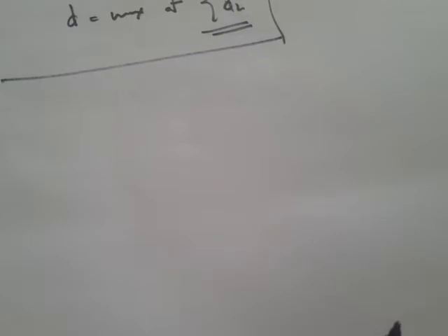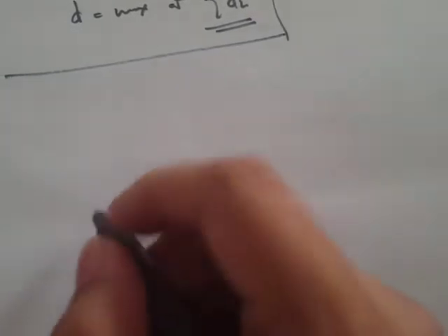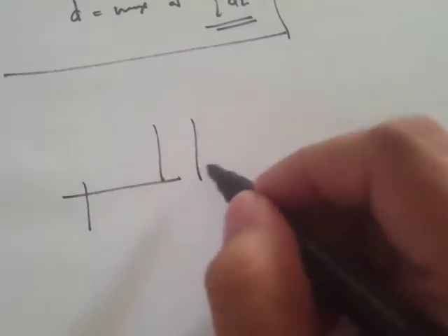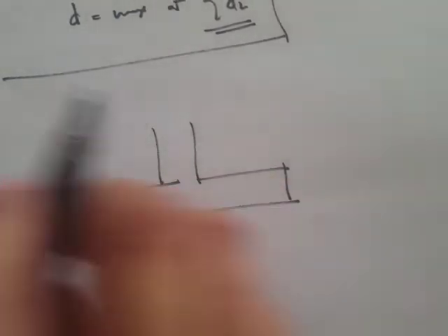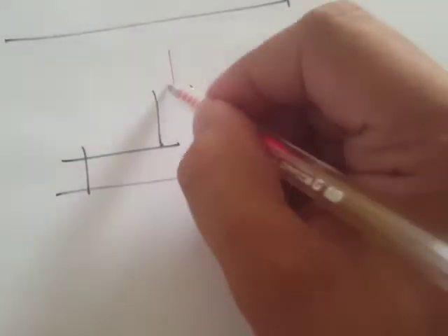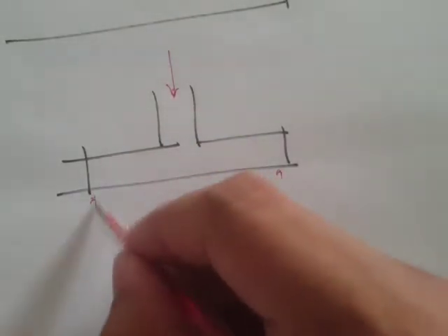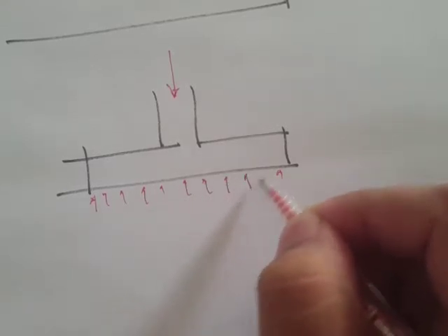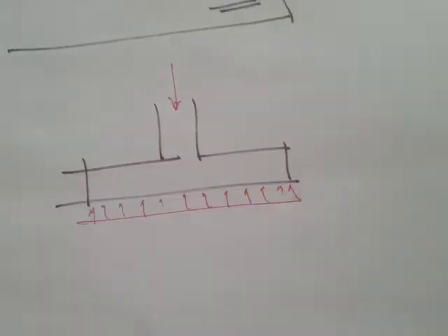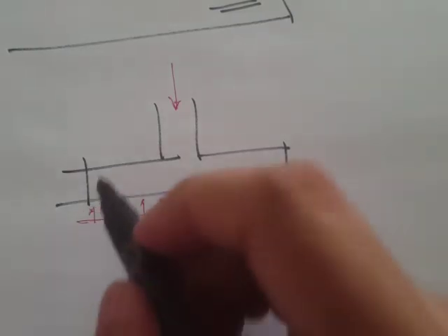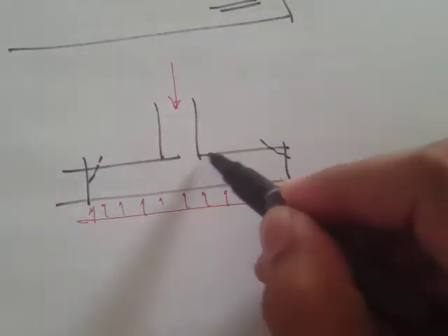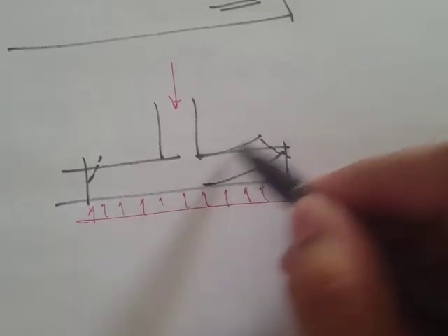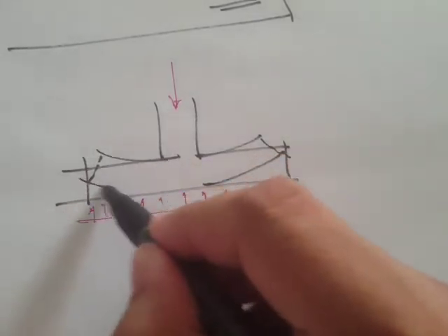Alright, so enough for the shear. Now let's discuss the flexural strength of the footing. This is our footing, and when it's subjected to loads, and let's say the pressure is also here, one tendency is to have a bending of this portion.